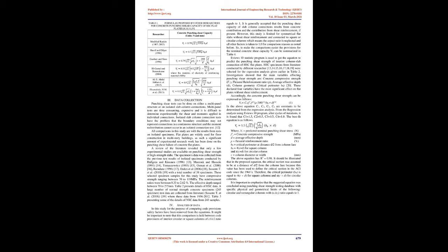The main purpose of this study was to propose a new simple punching shear equation for both normal strength concrete, NSC, and also for high strength concrete, HSC, flat plates, and to compare the proposed equation with the shear strength provisions of ACI 318-14, Eurocode 2, CSA A23.3-14, IS 456-2008 for interior slab-column connections without shear reinforcement.